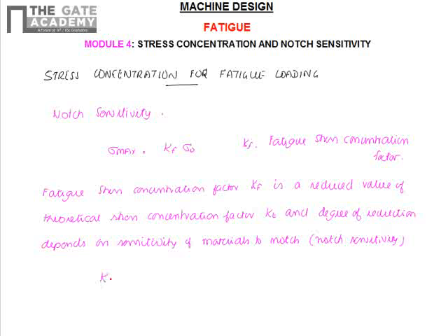Therefore, the fatigue stress concentration factor Kf is given as 1 plus Q into Kt minus 1.